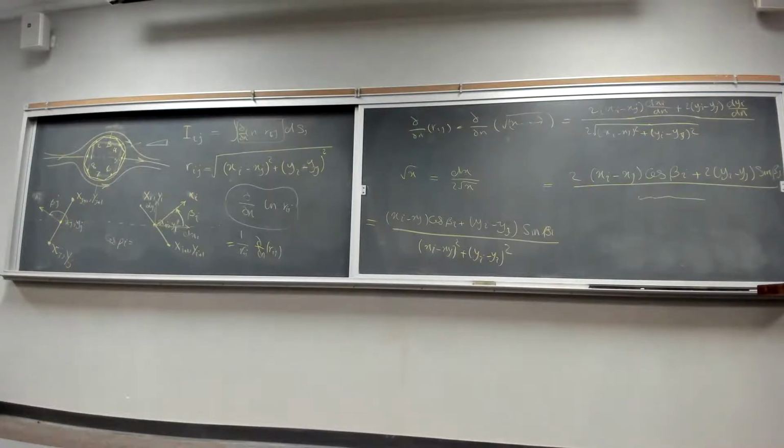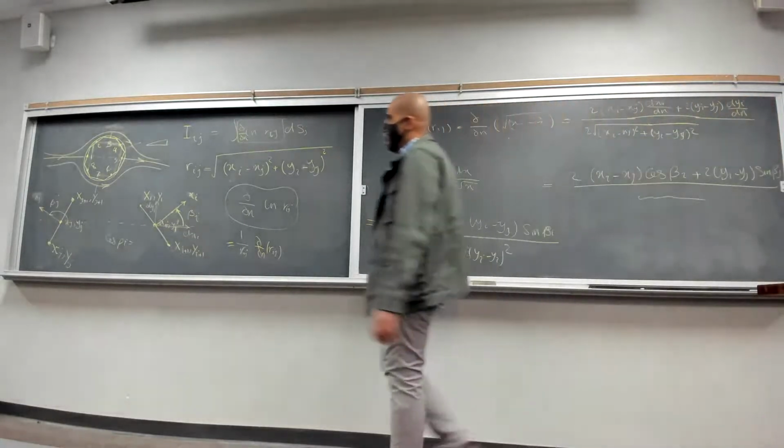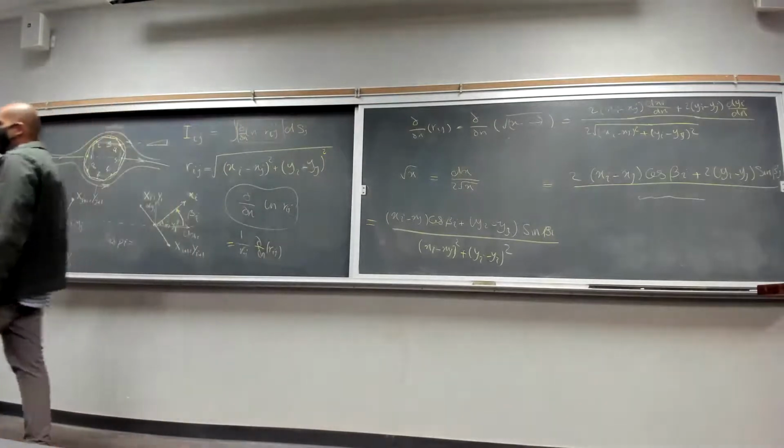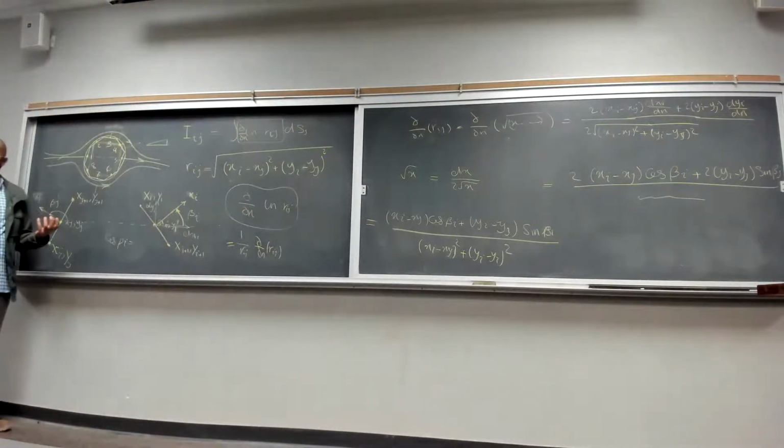I guess let's just stop here and finish this example in the next lecture, right? But eventually, what we are gonna do is to find an equation that gives us I of ij, right? And then using that, we are going to find the velocity potential as a function of lambda induced on each panel, right? I of 1, 2 will be one number, I of 1, 3 another number, I of 1, 4, I of 1, 5, I of 1, 6, all of those different numbers, right?